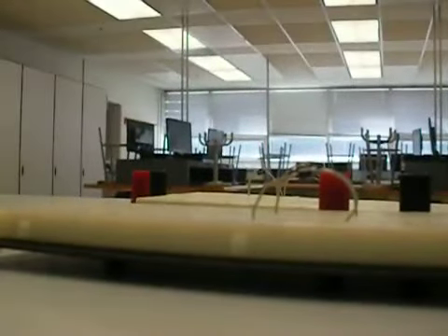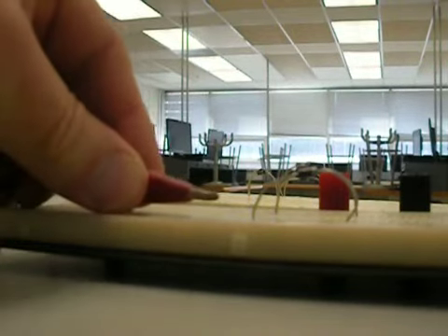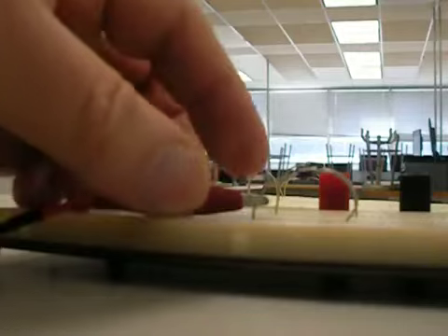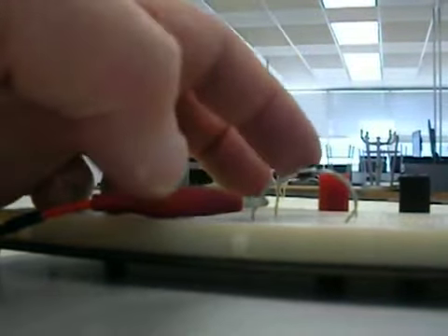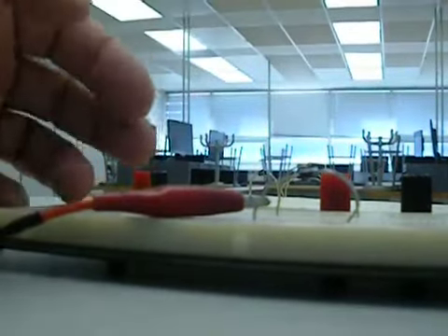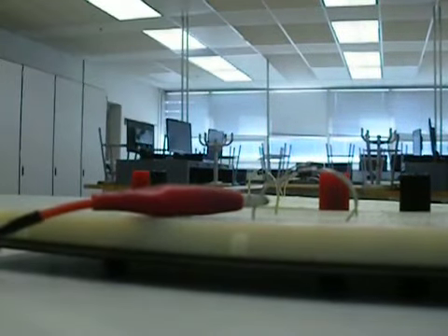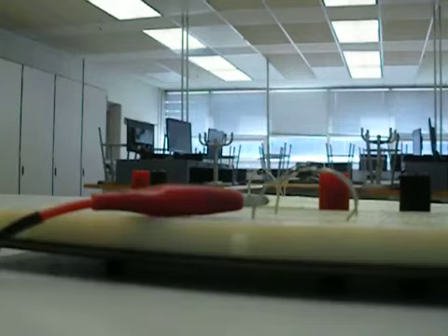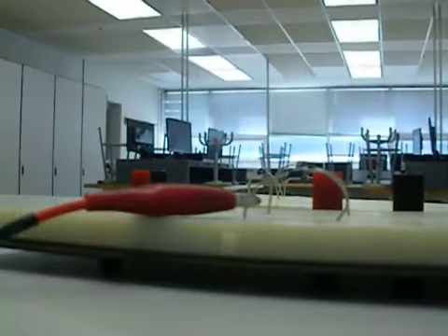So let's start hooking up diodes. Just for reference purposes, I'm going to connect the red one onto this diode, and I'm connecting it to the end without the stripe. The striped end of a diode is the negative end. The unstriped end is the positive end. I'm sending AC into it. It really doesn't matter which one I'm connecting it to, but if I send it into the positive end, on this end I will read positive voltage.